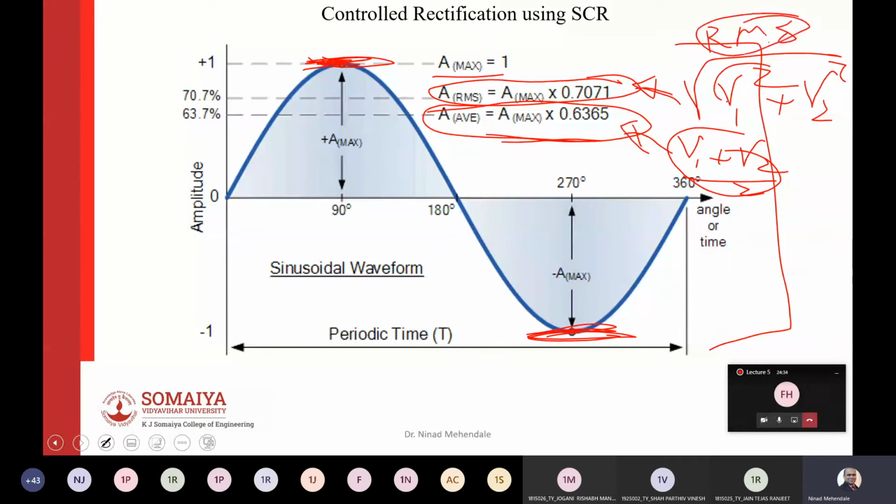The advantage here is that since you square, even if you have a negative voltage, it will get converted to positive. So negative and positive terms both get converted to positive because of the square, and then you add the two positive terms, and your overall value could be a representation of your power. That's why RMS values are typically more important than average values, because the average value could be zero also, but the RMS need not be for a particular sine wave.